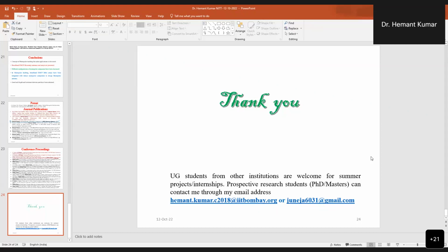And even RT Duroid substrate, you won't get it in India. You have to import it from the US. Okay, thank you, sir. So the main thing while deciding the substrate is you have to check at which frequency you are working, and for what applications you are designing, whether commercial, defense, space or satellite applications. For them, you need good accuracy, so you have to get a good, less lossy substrate. For commercial applications, these things won't matter, so you can use FR4 substrate as well.